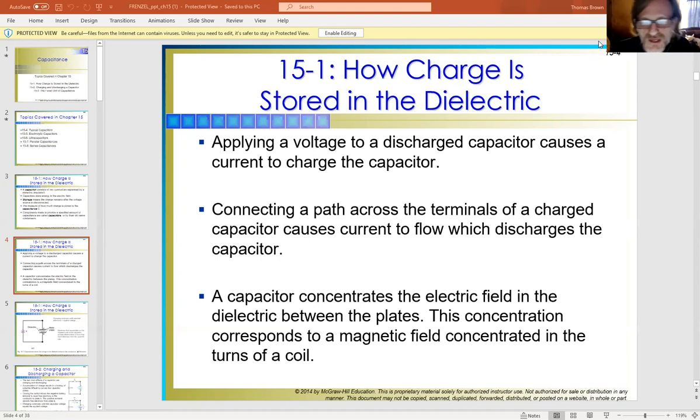But they work uniquely. The two wire leads that you'll see coming out of the capacitors, when you look at it internally, are not connected at all. They'll be separated, and between the two will be the dielectric material. It's different from capacitor to capacitor. Some have a mylar dielectric material within. Like the electrolytics, if you were to open one up, it almost looks like a roll of paper, with a shellacked material. The dielectric is coated on that, and it's all rolled up. In the beginning of it will be one wire lead, and at the end of the curl is the other wire lead. So the dielectric does separate it in between.